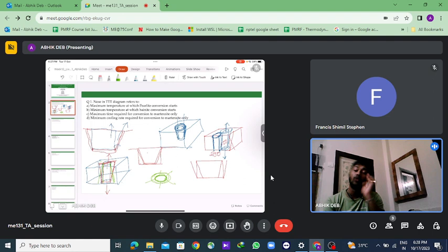First we will have the liquid shrinkage, then we will have the solid shrinkage. First we have the liquid to the solidification temperature shrinkage, like this liquid line to the solidification temperature. Then there will be solidification, this entire part, which is a phase change. So the entire thing is this, and then there is a solid shrinkage.